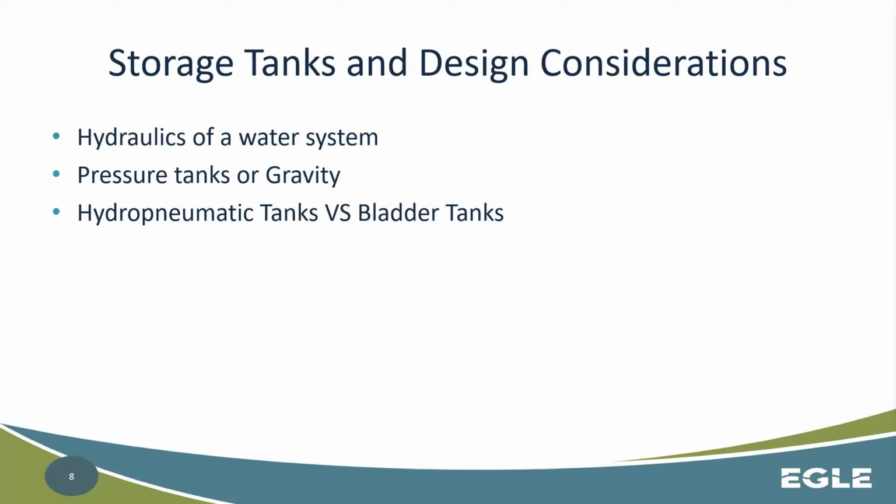Maybe you have a small system, so you don't need a whole elevated storage tank. Maybe you just need some pressure tanks, versus maybe you need something more. Maybe you need a lot of volume, so you put in a ground storage tank, but do you want that to be gravity fed, or do you want that to be with high service pumps? Things to consider. And then, if you're going with the pressure tank route, are you going hydropneumatic?